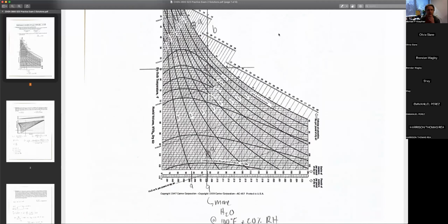If I have a constant amount here of the absolute humidity and I just cool it down, if I can draw a straight line, then it would make sense that nothing condenses until I hit 100% humidity, right? And that would correspond to where the wet bulb and dry bulb are the same, in this case 50, from where we draw it out in this problem statement here.